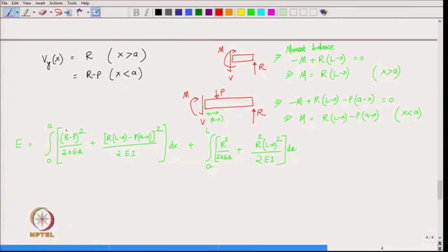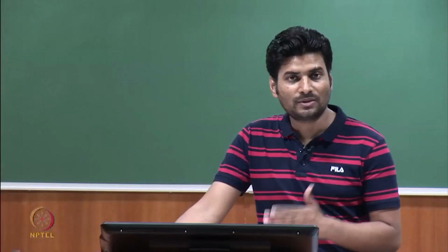All right, having written down the energy, we have to keep in mind that our goal is to get the reaction force. So, how do we get this reaction force R from here? We see that in the energy we do have the reaction force R. Now, if we want to use Castigliano's first theorem, what do you think would be the derivative of the energy with respect to the reaction force R? That is nothing but the corresponding displacement of this reaction force R,